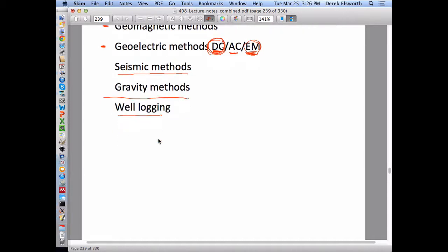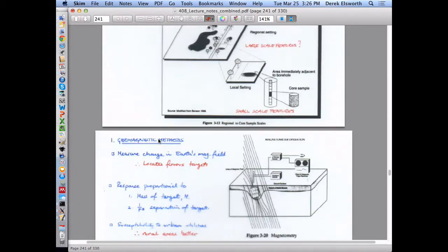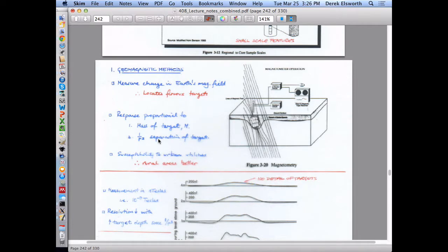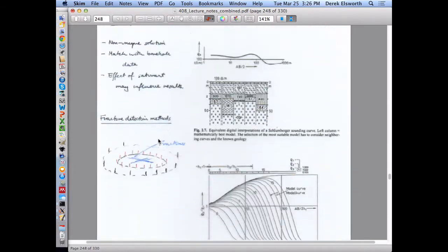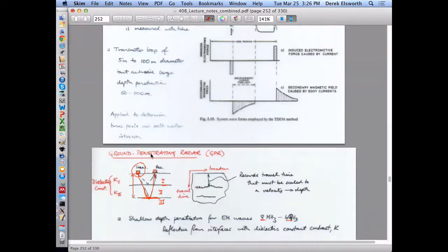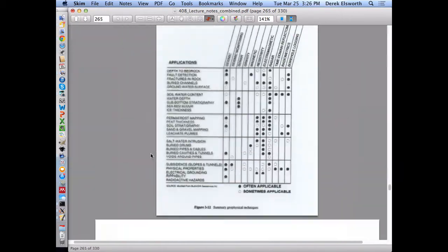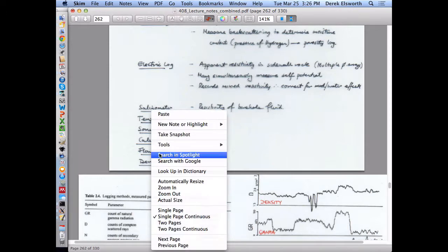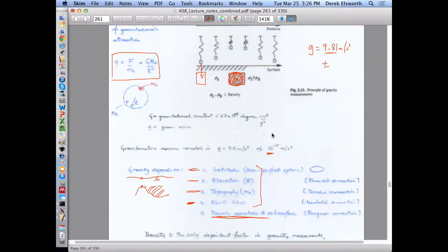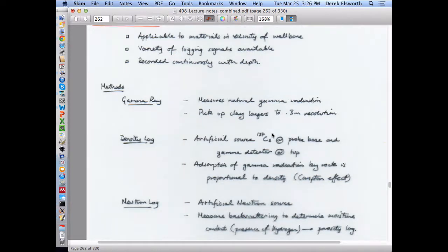We made the point that often when you drill, sometimes if you drill wells by percussion methods, not rotary methods that take cores, not augering methods that also do sampling, but straight tricone drilling methods that don't actually take a sample, then you physically don't really have much idea of what's down there. Maybe you get the chips that come up in the drilling mud that you can look at to see what the different materials might be. And also you could put a borehole camera down there to see what the rocks look like after the fact, and maybe look for fractures, which you can certainly do.